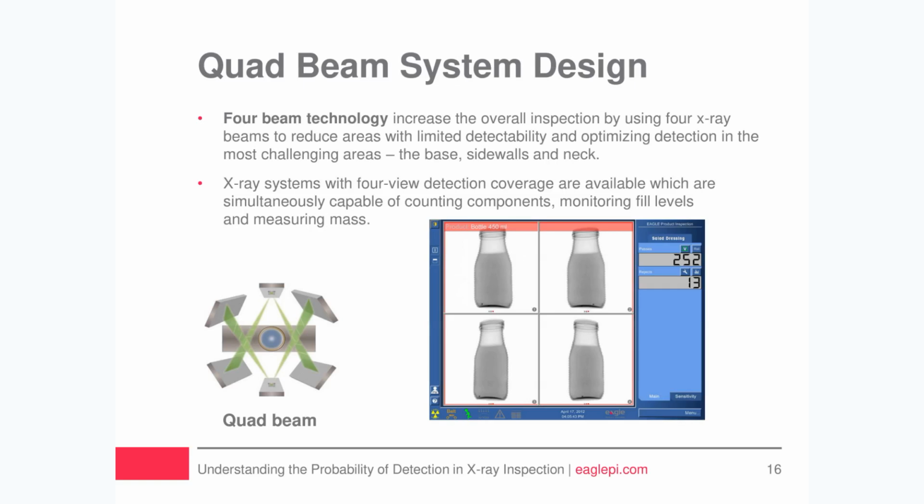And if this packaging supplied by different manufacturers is run intermingled, this can severely affect the probability of detection, contaminant sensitivity, and the subsequent false reject rate. When different manufacturers of packaging are involved in a product line, you have to be particularly careful that they are identical, and if they are not, sometimes different programs have to be created for when you run different manufactured packaging.